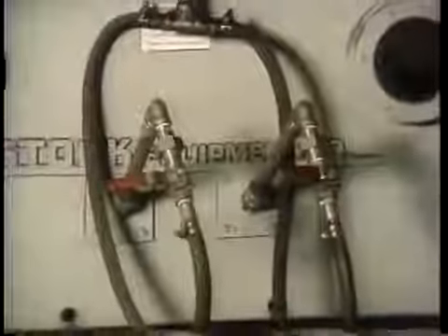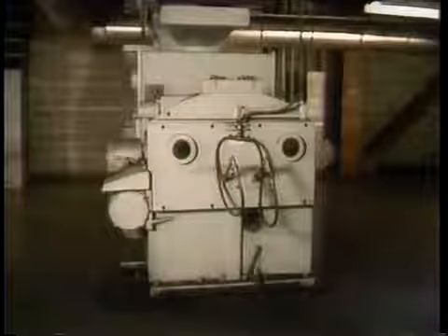The fires that we've discussed occur inside closed equipment. In many cases, there are access doors on these pieces of equipment that allow maintenance to be performed. If an equipment fire is suspected, under no circumstances should an access door be opened. By leaving access doors closed, you increase the likelihood that the fire will consume all available oxygen and eventually smother itself. Opening an access door has exactly the opposite effect. An immediate supply of oxygen is made available for combustion, which could make the fire worse or even cause an explosion.